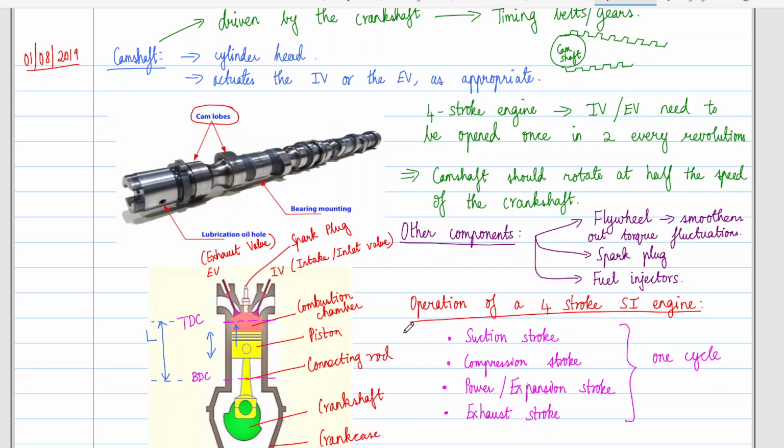Now, if I were to think as a designer, how will I decide how many rings I need to put? If for some reason I want to raise the pressure at which we will be doing combustion, say by adding a turbo, in such a scenario I may need to either make my rings slightly bigger or maybe add more rings to do the job, right?